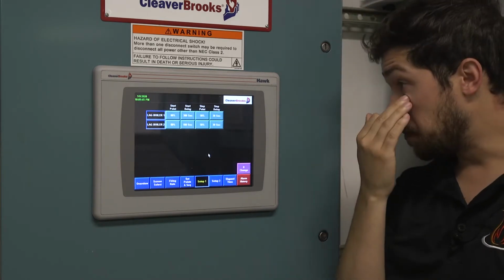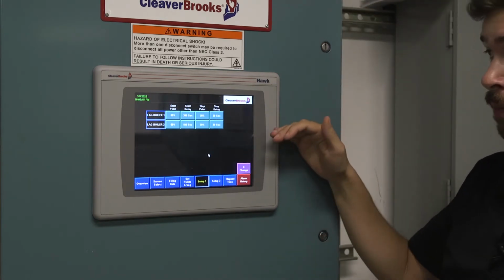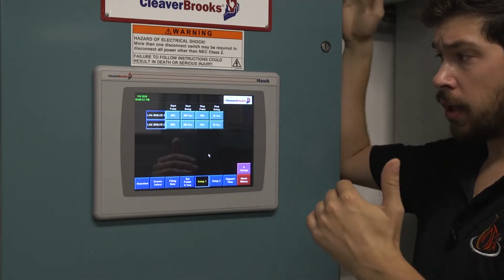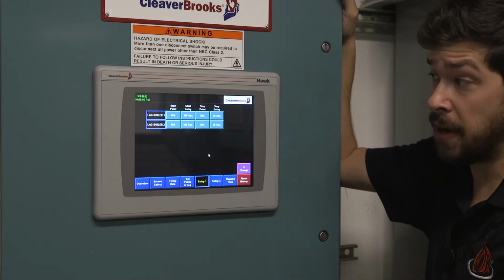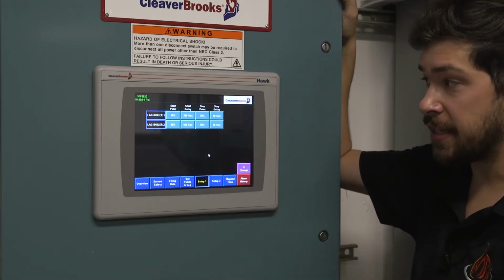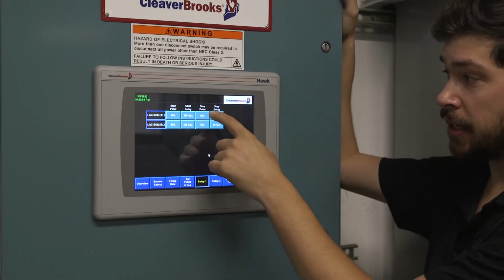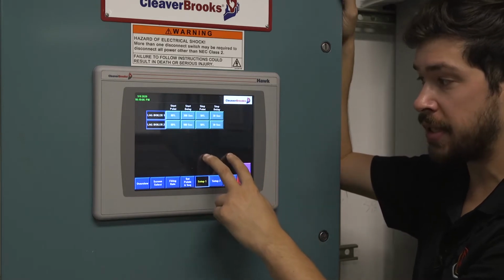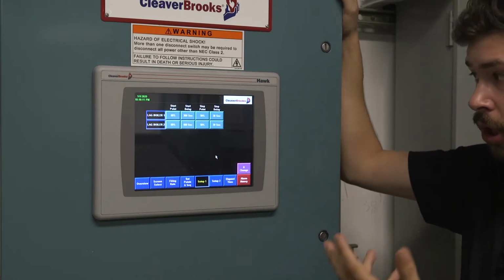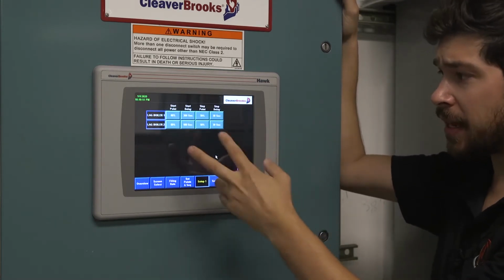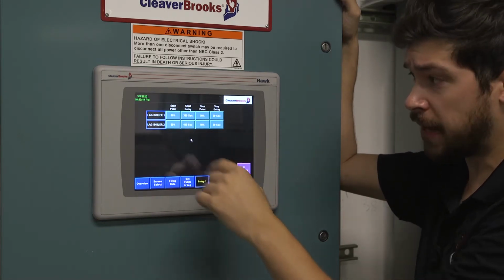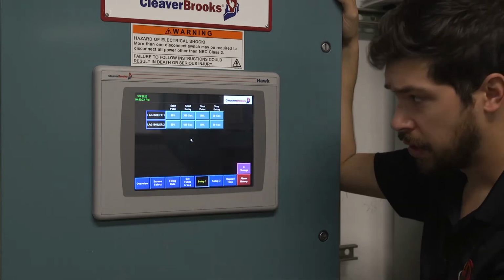So great, we went from, say now 90%, the first boiler firing at 90%, and then comes down to, both boilers would then come down to about 50%. So we then wait 30 seconds at that point. The stop point would be if both boilers then dip below 50% for an extended period of time, longer than 30 seconds. Same kind of deal with the next lag is if both boilers get to above 80% for longer than 180 seconds, starts the third boiler.